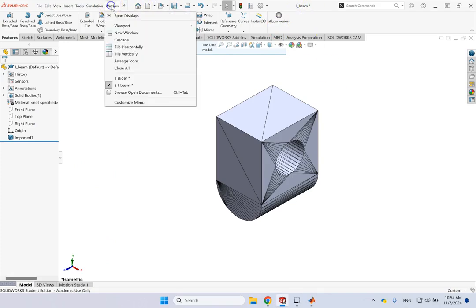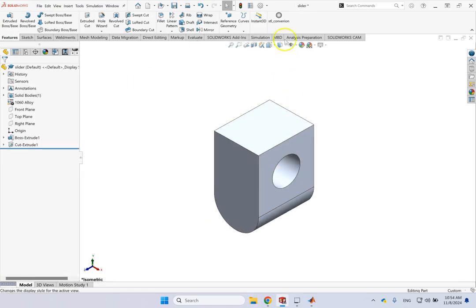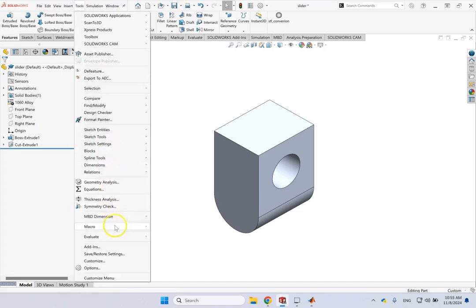actually this is a slider really. So it should pick that name, slider, and save it as slider.stl, or ask you for something, so you can add more and modify it. But you see the overall idea. Here I created my custom button, and now with this custom button I can save my file to anything I want just by simply recording a macro.